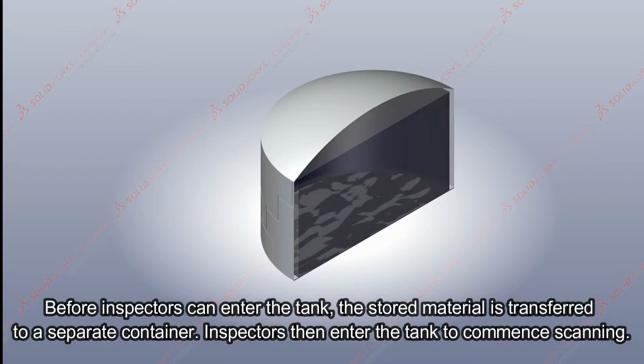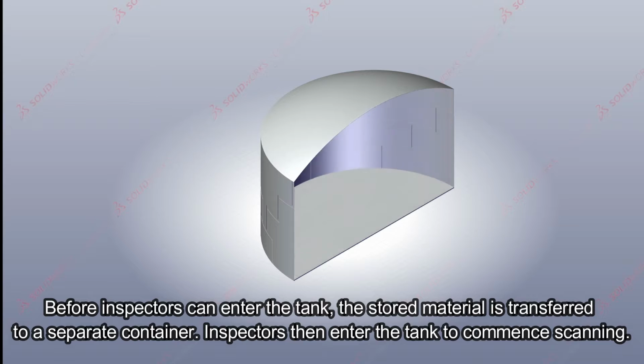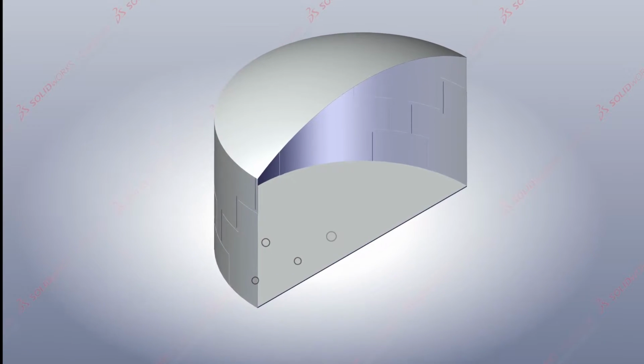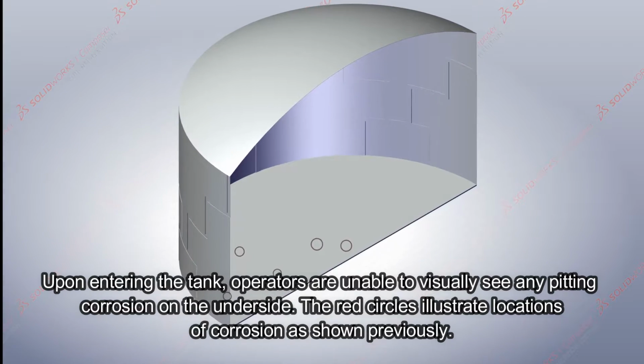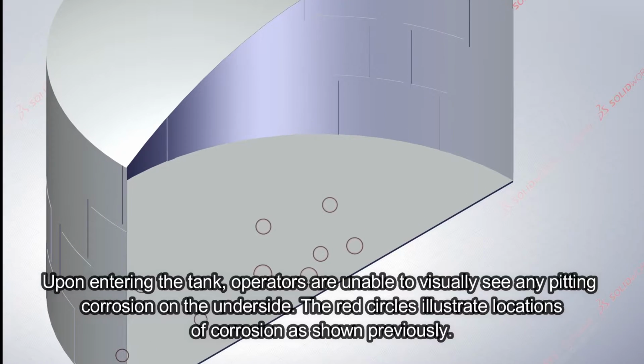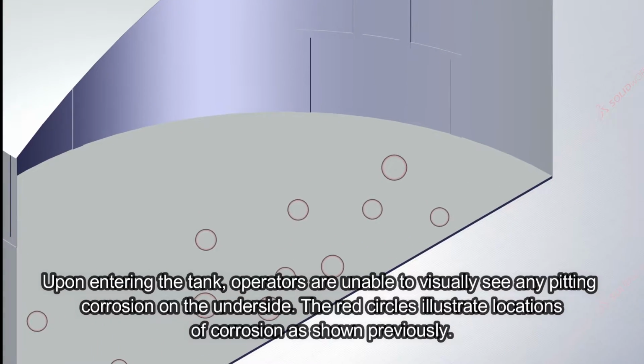Before inspectors can enter the tank, the stored material is transferred to a separate container. Inspectors then enter the tank to commence scanning. Upon entering the tank, operators are unable to visually see any pitting corrosion on the other side. The red circles illustrate locations of corrosion as shown previously.